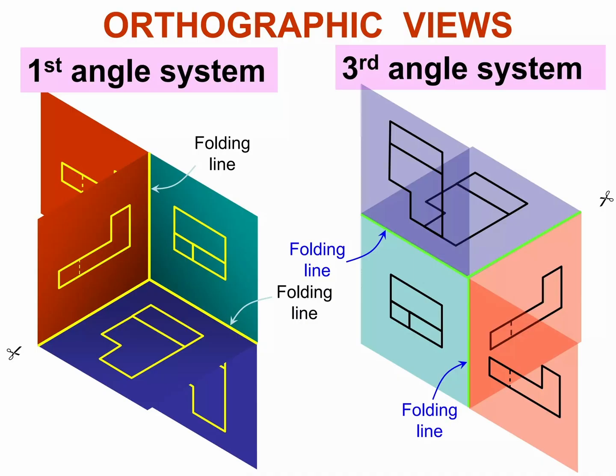So let's talk about third angle and first angle. This screwed me up for the longest time. I never did quite understand why they did this, but this is what happened. Just remember, third angle is basically standard in the US right here. Everything is front side, the top side is above the front, and the right is on the right. Pretty obvious. Front, top, right side. And it's on the right side, so it makes sense that way.